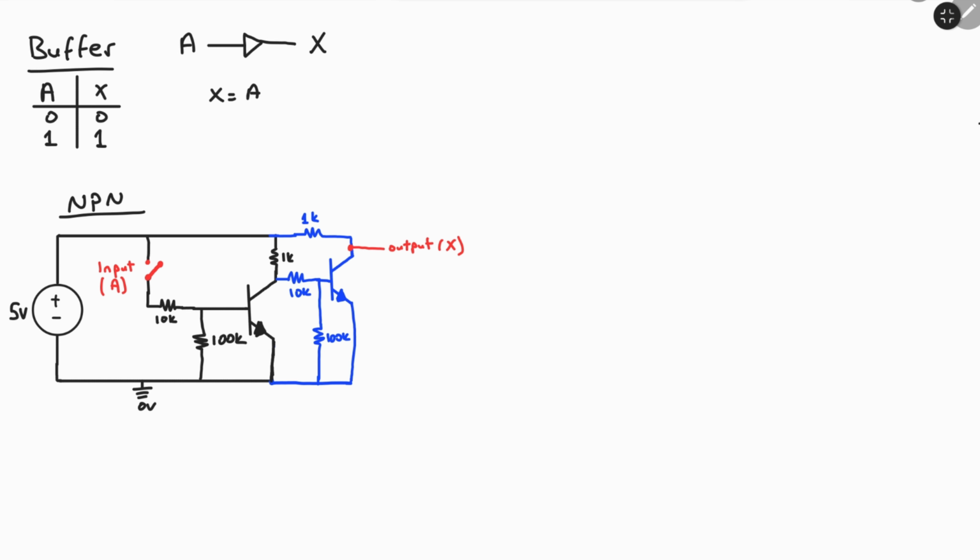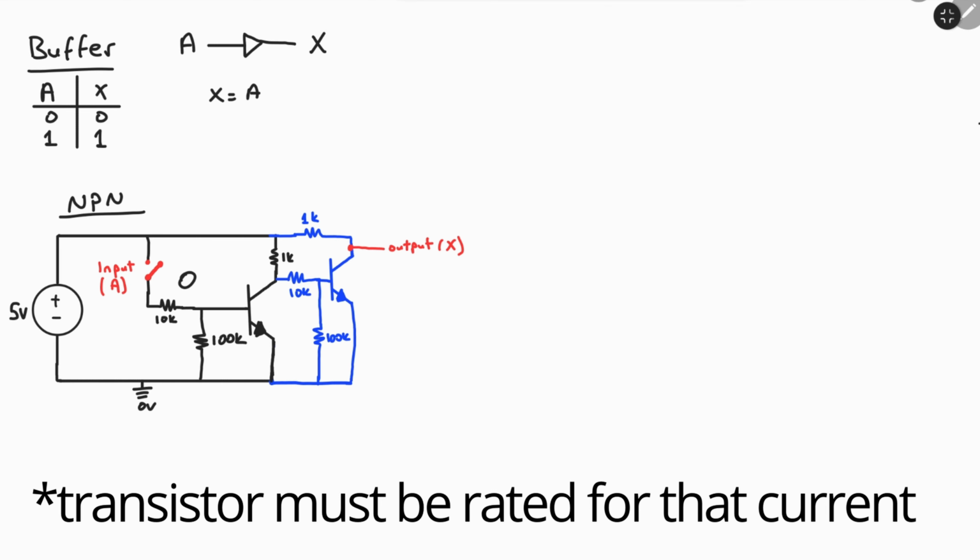Another useful thing with the buffer is that the gain is quite high. So you give a tiny current here, you get a huge current passing through here, let's say maybe 15 times more. And this 15 times current gets multiplied 15 more times here, so you get 15 squared current passing through here. So it has some interesting uses.